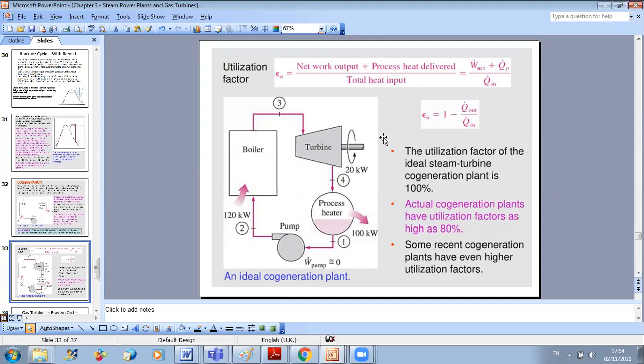Okay, then in this case, first, we will produce electrical energy through the use of the turbine. And second, we can use the heat that is lost at the condenser level in any application that requires heat. So in this case, our efficiency will be much increased. And of course, in the ideal case, we can reach 100% efficiency.